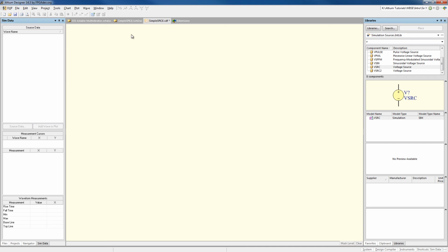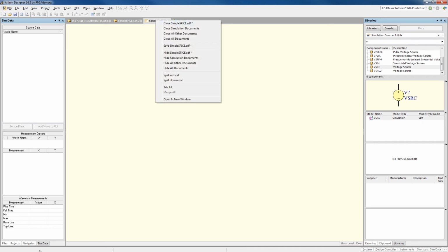So let's do one other thing here. By the way, what I was going to mention with the sim data panel is that this panel always comes up when you're doing SPICE simulation. So whether you're doing this with the Webench or with Altium Designer directly, it stores all the points of data for all the nodes. Even if there's one that you didn't want to capture a waveform on, you can drag it over there. In some cases it did preserve that information. You can bring it in.